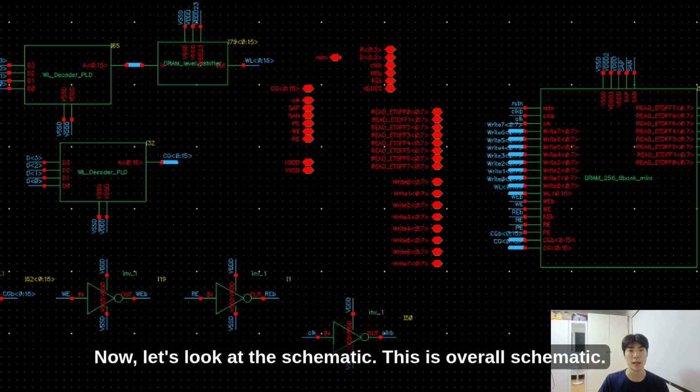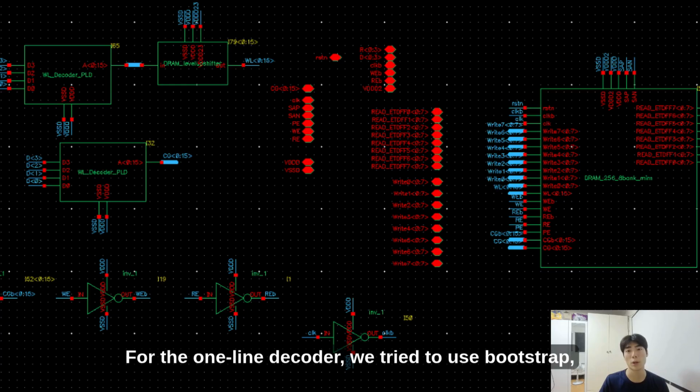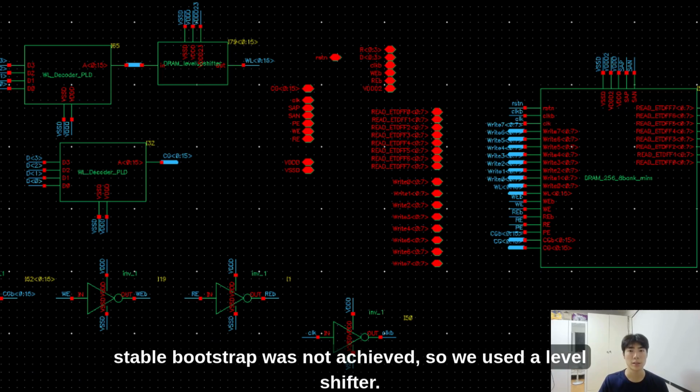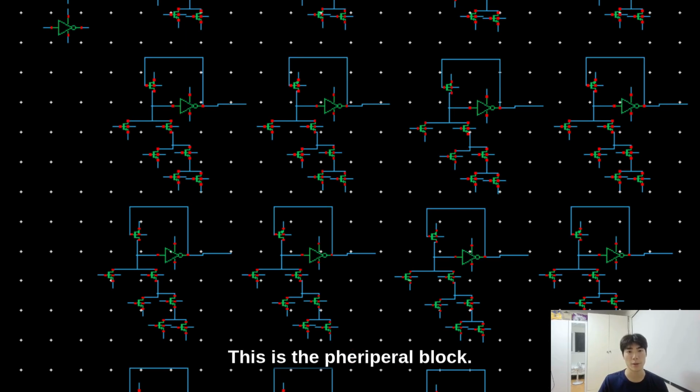Now let's look at the schematic. This is the overall schematic. This is a column and row decoder. For the word line decoder, we tried to use bootstrap, but due to parasitic capacitance, stable bootstrap was not achieved, so we used a level shifter.